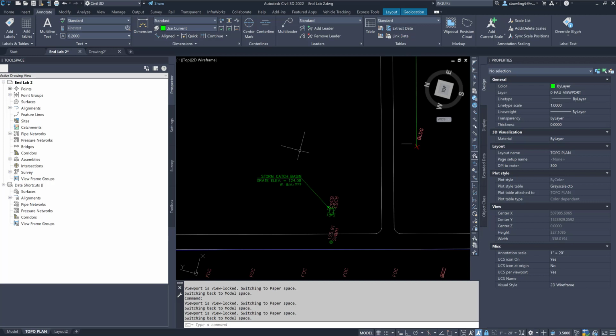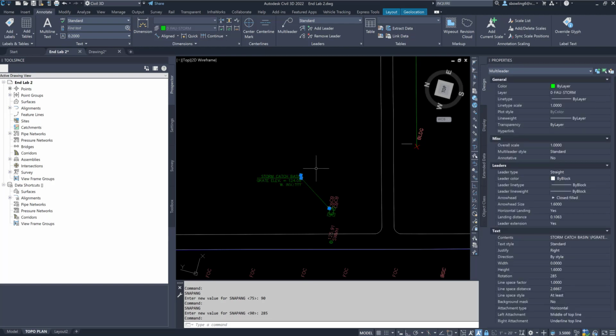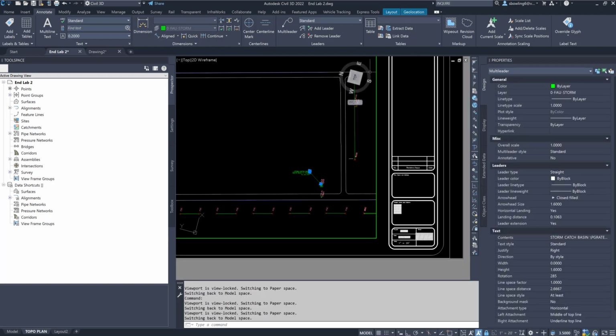Okay. Now, here's the thing: I am going to also notice my rotation here. It's got an odd angle. My crosshairs. I'm going to type in snap ang, and I'm going to type in 75. Okay. Snap ang 90. I'm sorry, it should have been 285. Okay, so the reason it's 285 is take 360 minus 75 is 285. So 285. There's my ortho. I'm showing you a lot of information because nothing's ever perfect in rotation. So I'm showing you a lot of different things in this exercise.